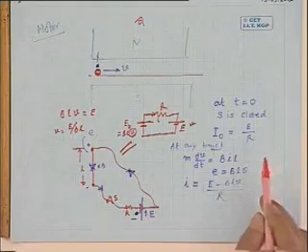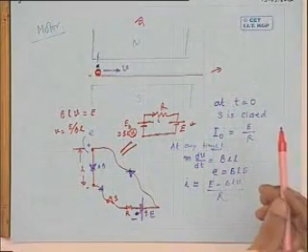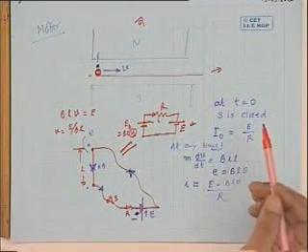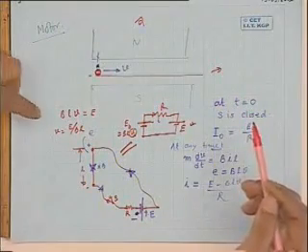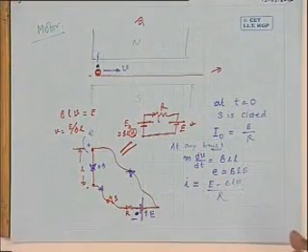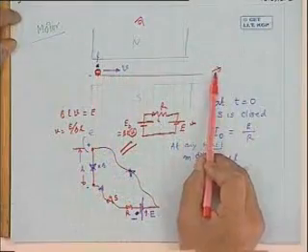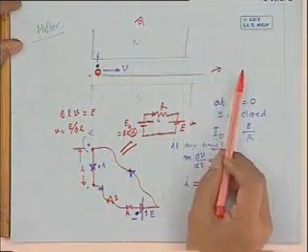And how much force is developed by the conductor at that time, when steady state is reached? 0. And if the rail is frictionless, it should not bother us. It has accelerated, so you don't require any force to move it with a constant velocity of E by BL from left to right. So you have started this motor and it is moving with a constant velocity like this.